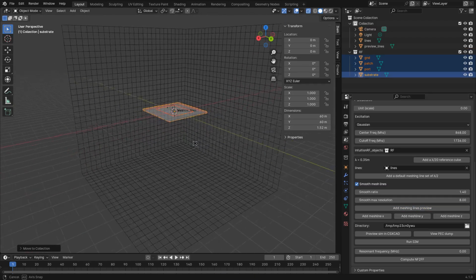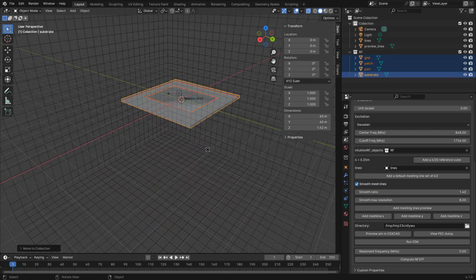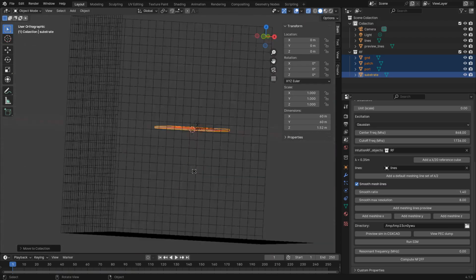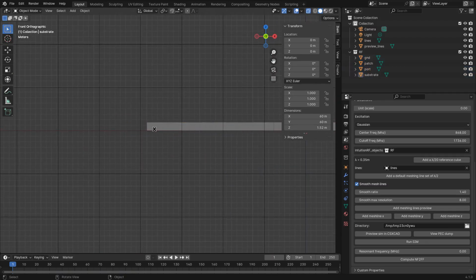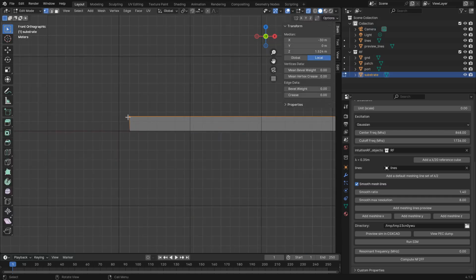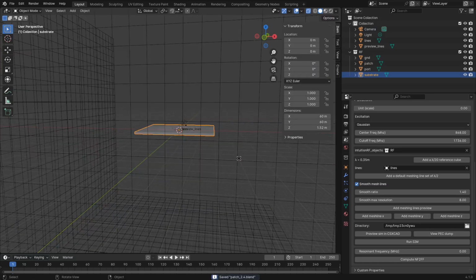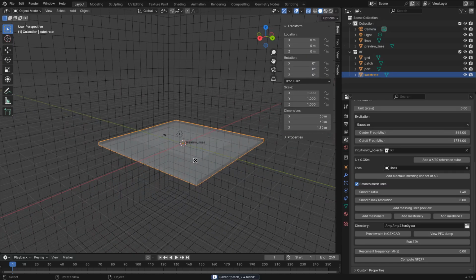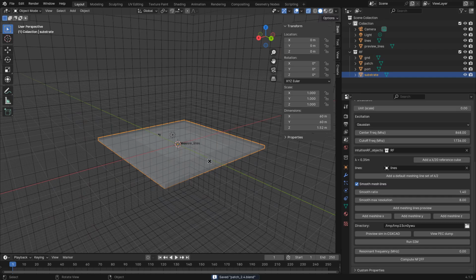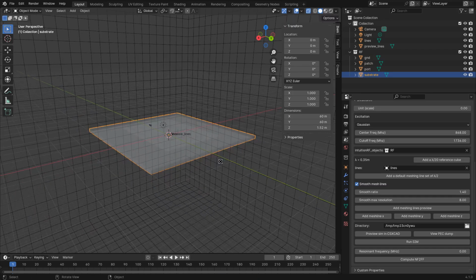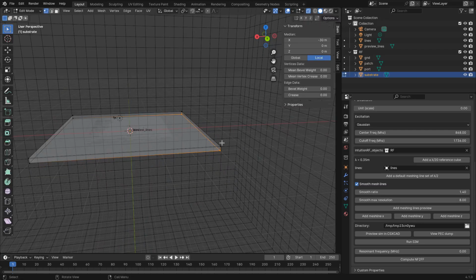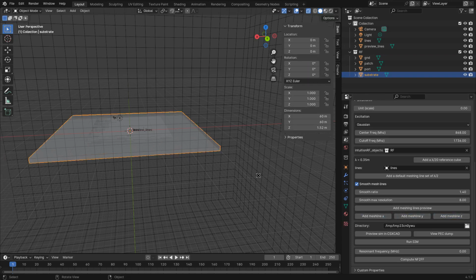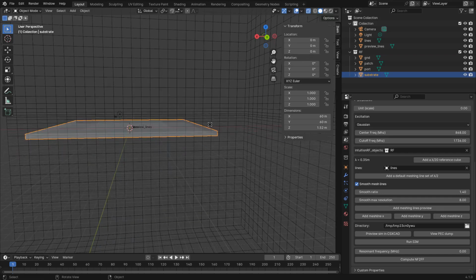Okay. So now you see we have default meshing lines. It does not match our geometry. We want meshing lines on the edges of our simulation. So one line like here, one other here. So we will need to add meshing lines to the simulation. There are two ways we can do this in IntuitionRF. The first way is we can select the vertices and click add mesh line X, Y, and Z here. And if I do this and preview again, you see the meshing has changed.